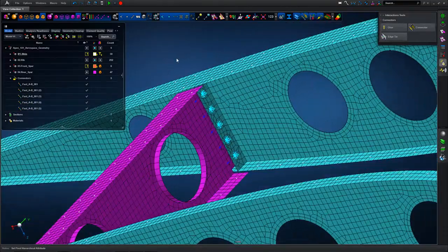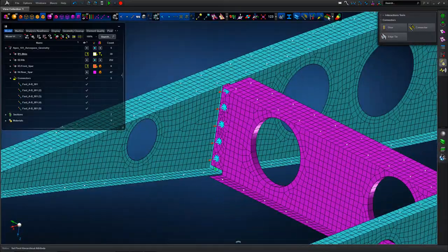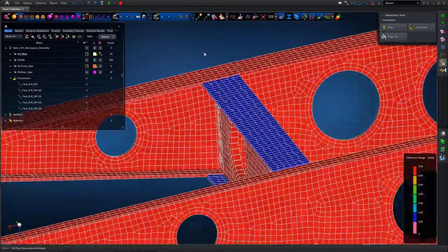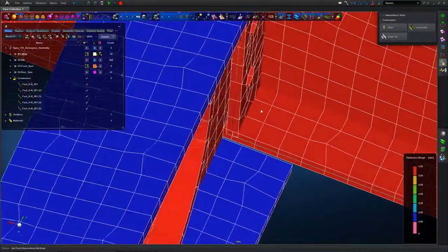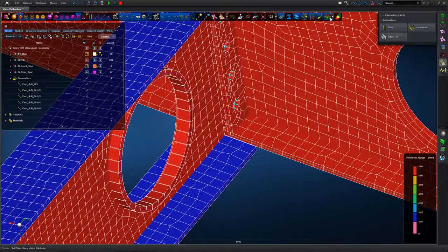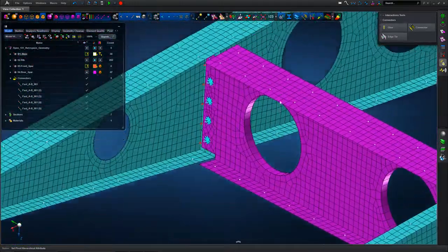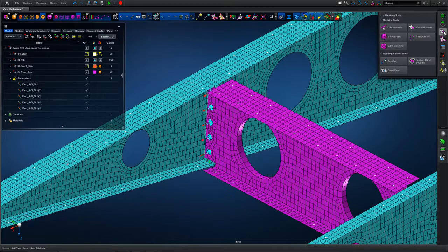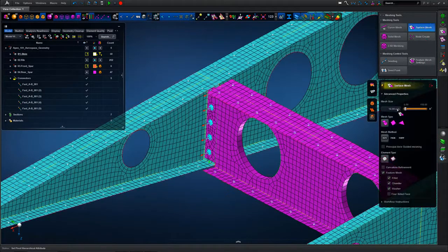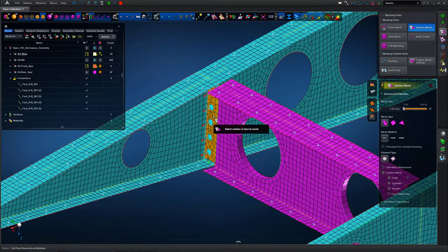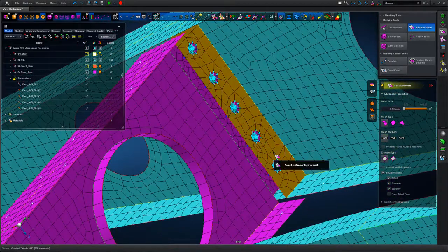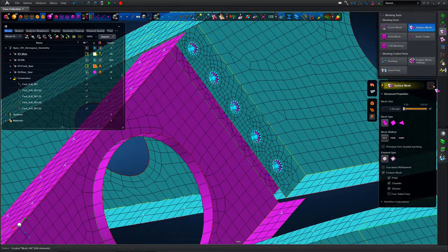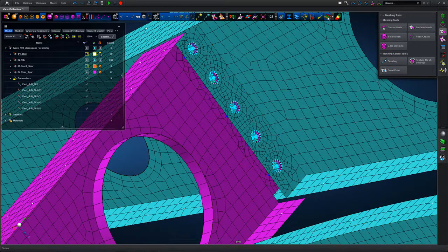So in this particular example, we've defined those connectors as we want. We can look at the shell thickness, that's unchanged based on the fastener definition, and then we can look at potentially remeshing the structure. So in the area where we've got those fasteners defined, perhaps not the best quality mesh, so we can reduce the element's edge length, and we've got a feature mesh setting turned on so that we get a nice ring of elements around each fastener, so perhaps a bit more appropriate in terms of looking at the load and the stress distribution around the fastener hole.